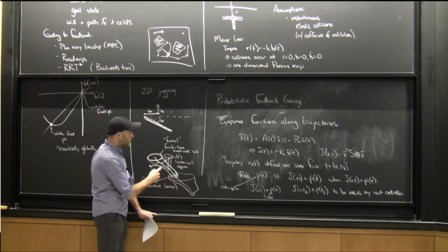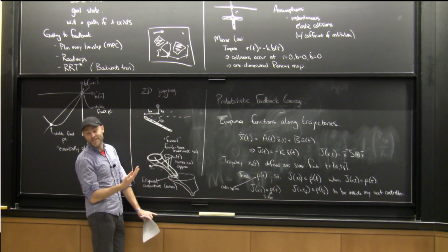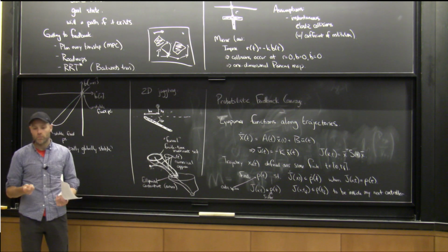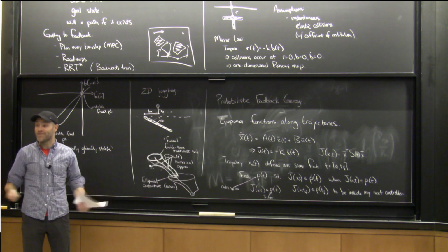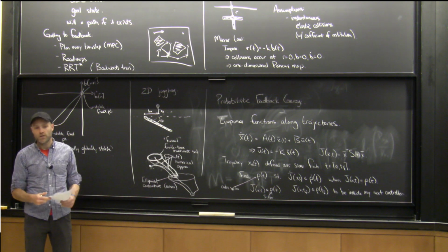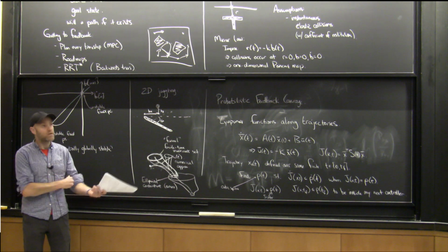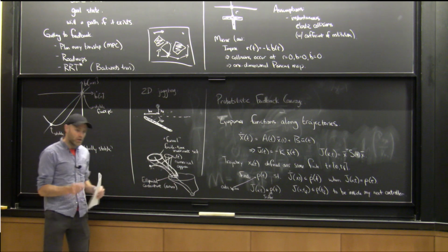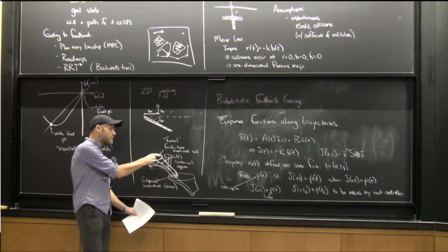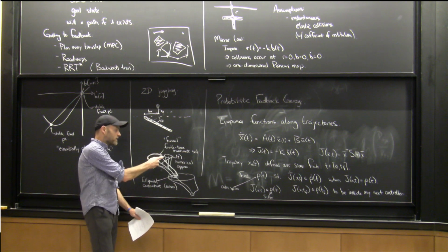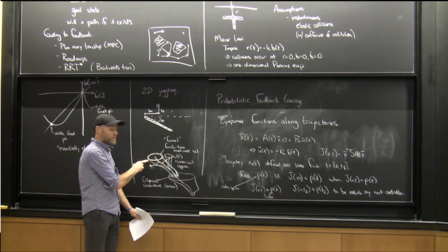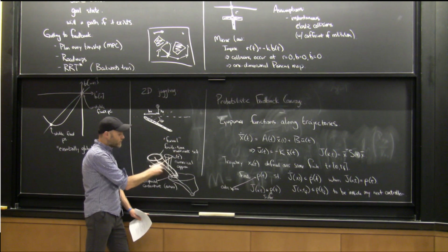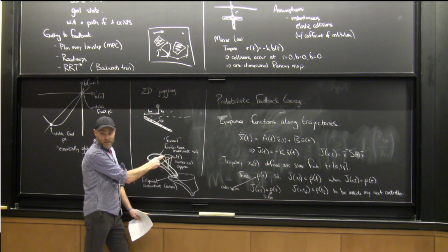Sorry. Okay. So now I have a finite amount of computation time, right? And I want to fill the space. So it's the same as an RRT, basically. Up to your patience, you try to fill the space. You go and execute. We have versions of this. In fact, the cartpole one was a simulation-based one, where once you put it on the experiment, if you ever found yourself outside the funnel, you could still use these funnels, which also produce a distance metric over the state space. They have a natural covering where you can ask all the neighboring trajectories what they think the cost to the goal is, right?